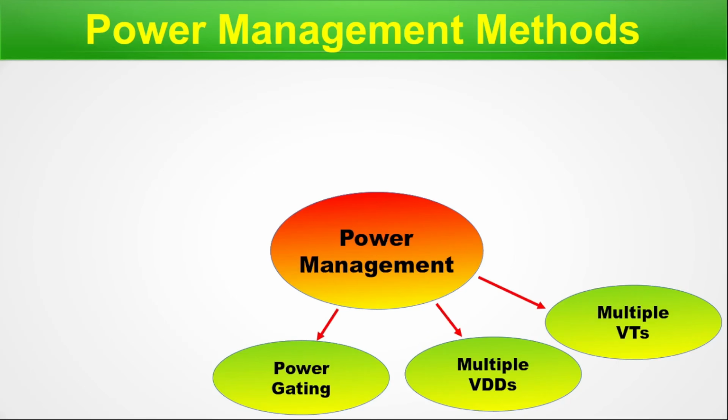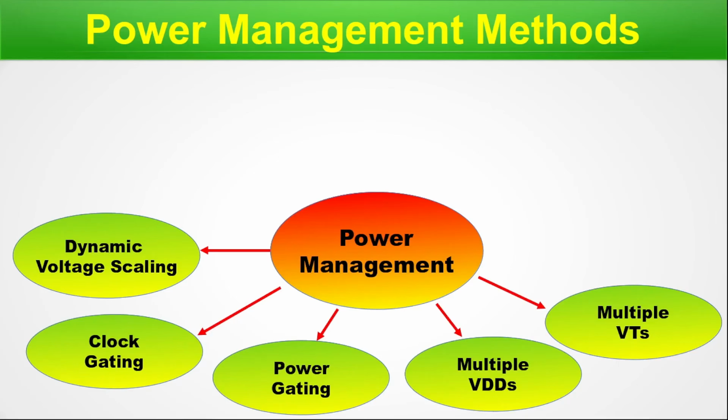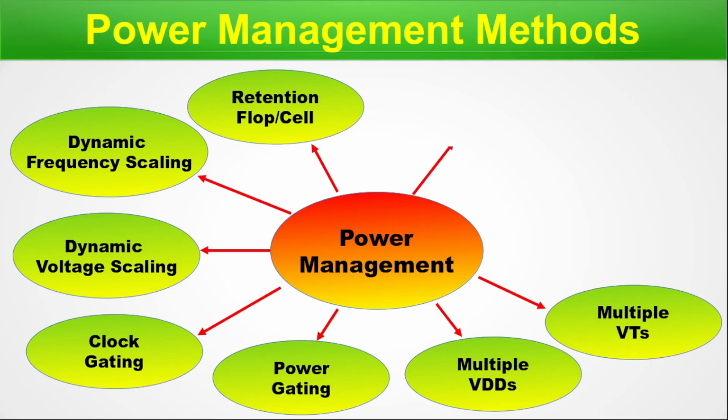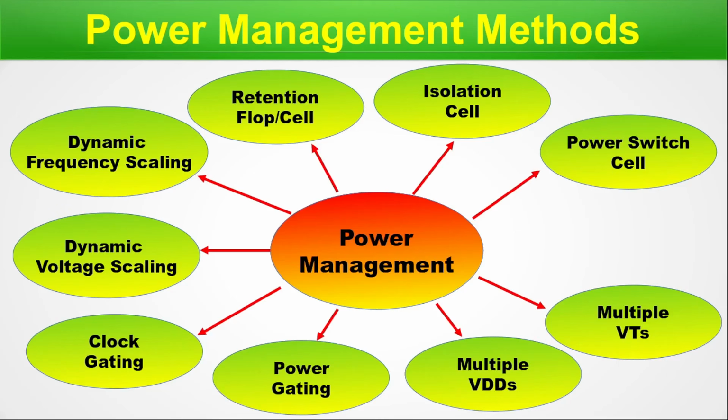Power gating is a technique by which also we do the clock gating for the power management. Next, another important way of power management is dynamic voltage scaling. We have another similar scaling called the dynamic frequency scaling, which is used for power management. Next, we have retention block or cell that we use in design. We use the isolation cell also for the power management purpose. We do use a power switch cell in the power management.